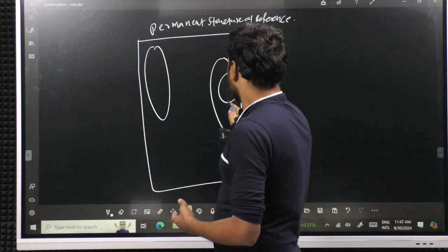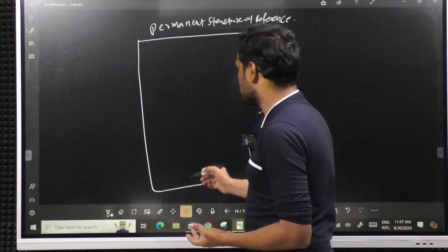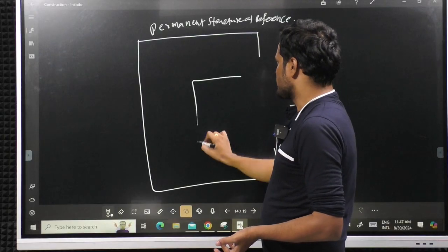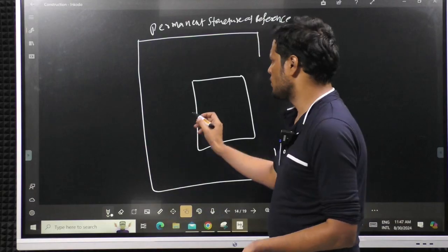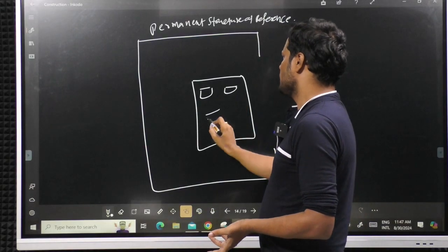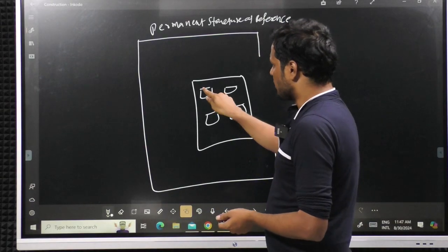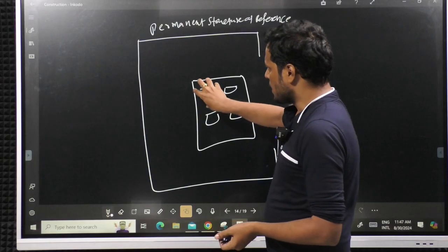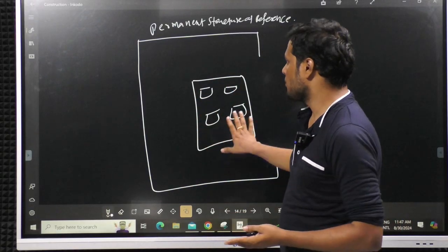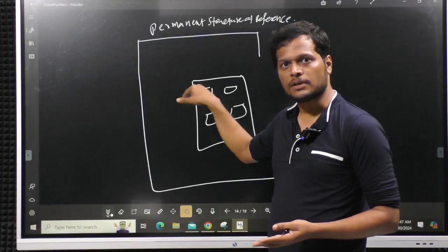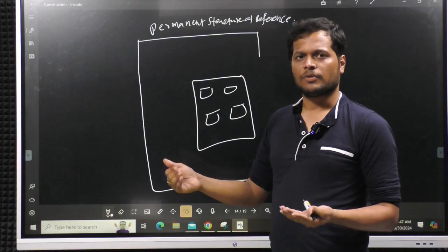Now coming to execution, suppose this is the part I want to execute. In some sites individual footings will be excavated. In other sites, marking for each individual footing will be placed and each footing will be excavated. In some cases the entire area will be excavated and the footing marking placed underneath. There are different ways to execute this.